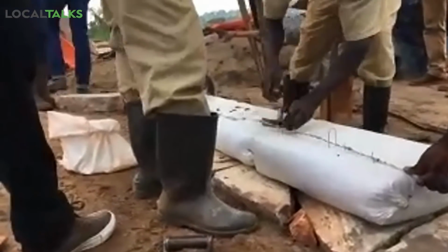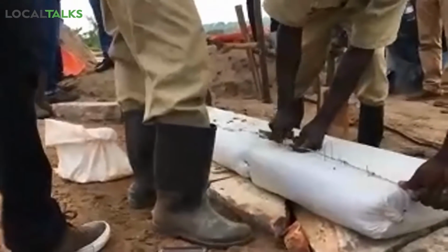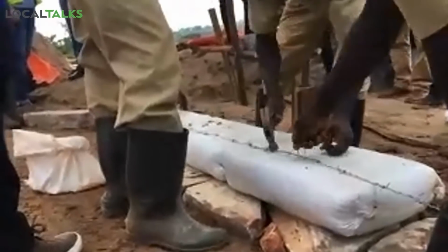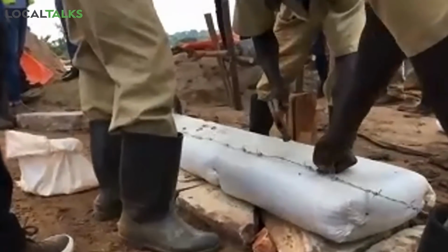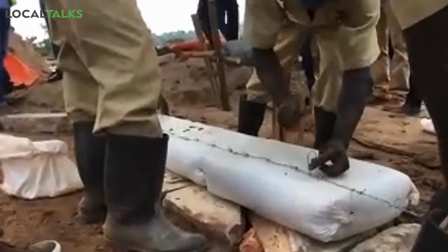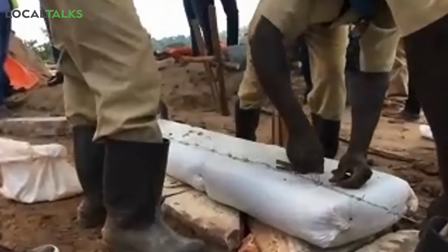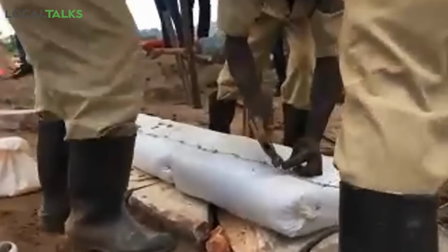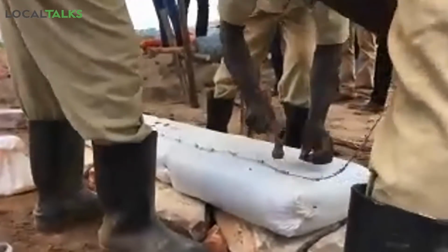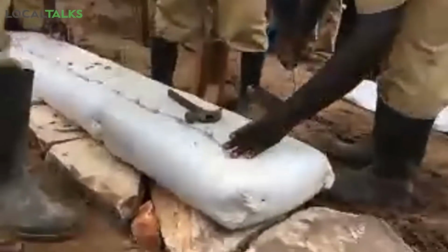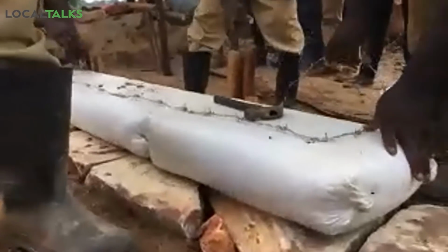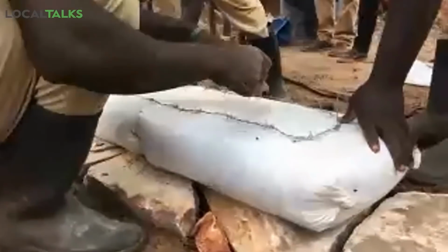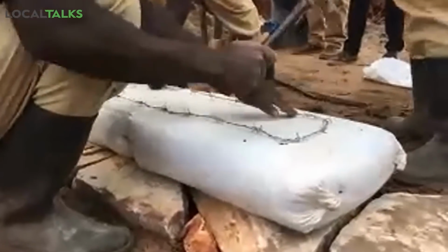Edson, would this technology work without barbed wire as well? Well, it would work, but there's a risk of these bags slipping, as the surfaces are quite smooth. During construction, or even afterwards? Afterwards, in terms of wind, earthquake, any ground movement, slipping could happen. You really need this barbed wire to ensure a proper shear strength, and for it to work as a unit.